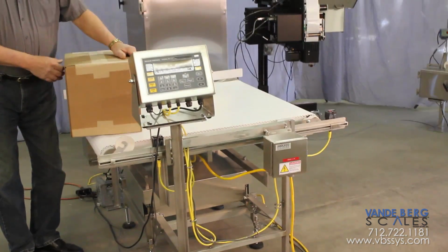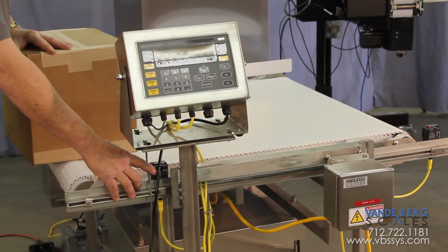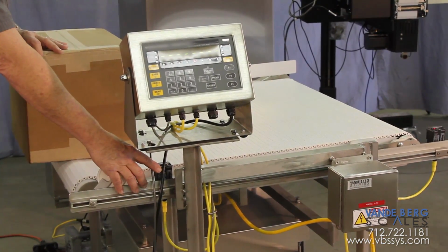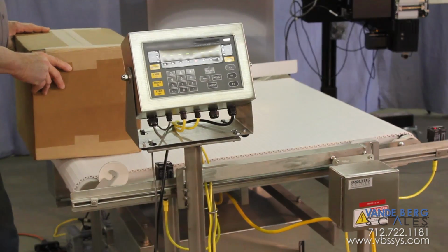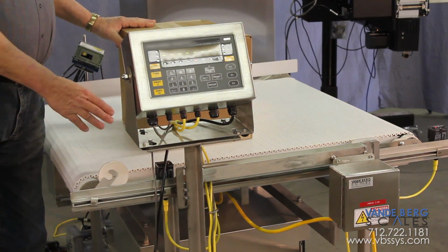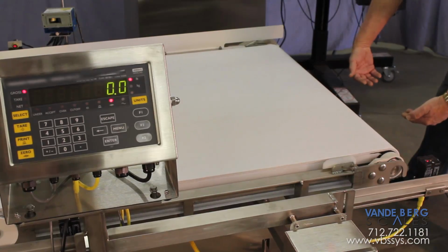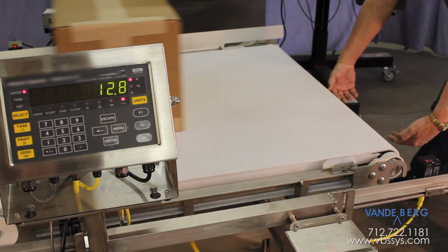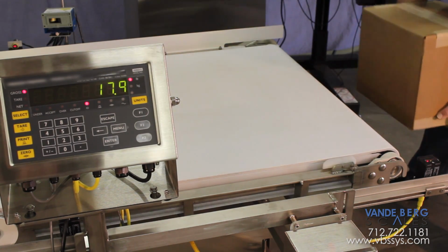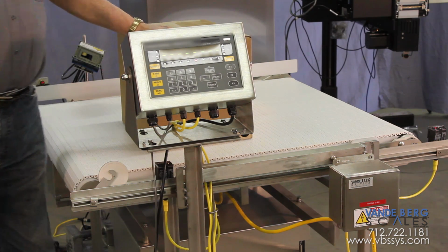Now, as the case is traveling on, you'll see a photo eye here on the in-motion conveyor scale. What this photo eye does is tell us we are about to start weighing. As the box travels, it opens up, weighs the product, and on the other end of the scale, we have the other photo eye that tells it to stop weighing. In this distance, we catch the weight of this product, which is legal for trade.